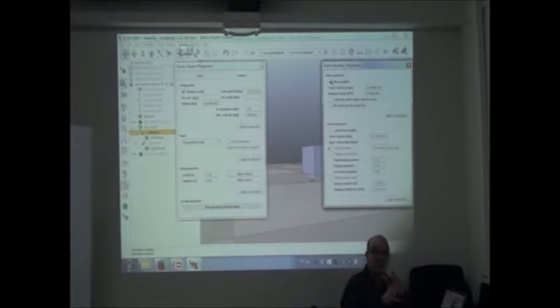Yeah, this is not a passive joint anymore. Now, this is a motor. I will check lock motor when we are at 0. It means it's not a back-drivable motor. And I will put a target velocity here of 10 degrees per second. Okay? 10 degrees per second. Let's do that on the other wheel too.